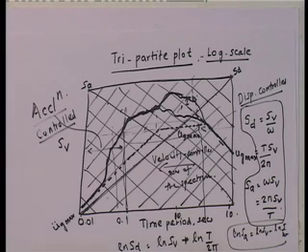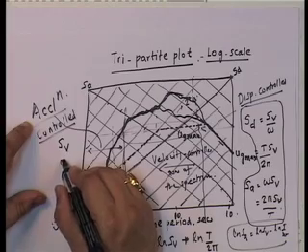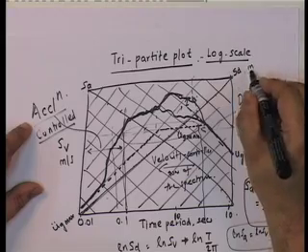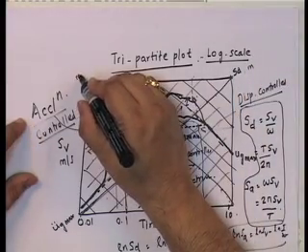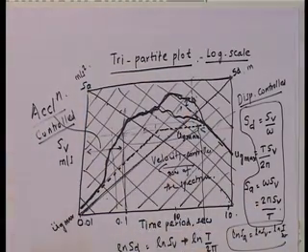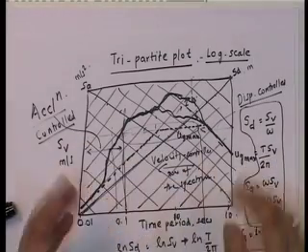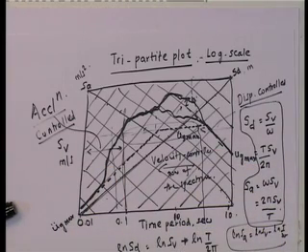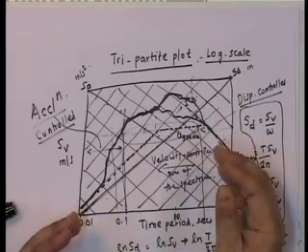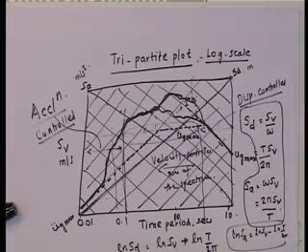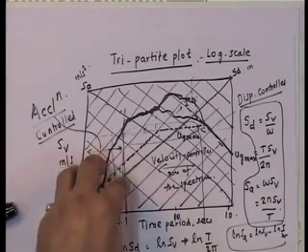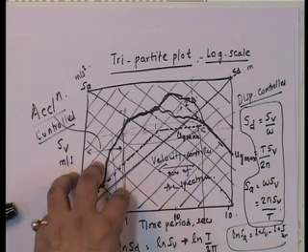And this is in meters per second, this is in meters or millimeters, and this is in meters per second squared. These are the units, okay. And the way this graph is plotted, it gives you very much where the acceleration controlled region is, where the displacement controlled region is, and the central is where the velocity. So, in other words, inertia controls all structures in this area.